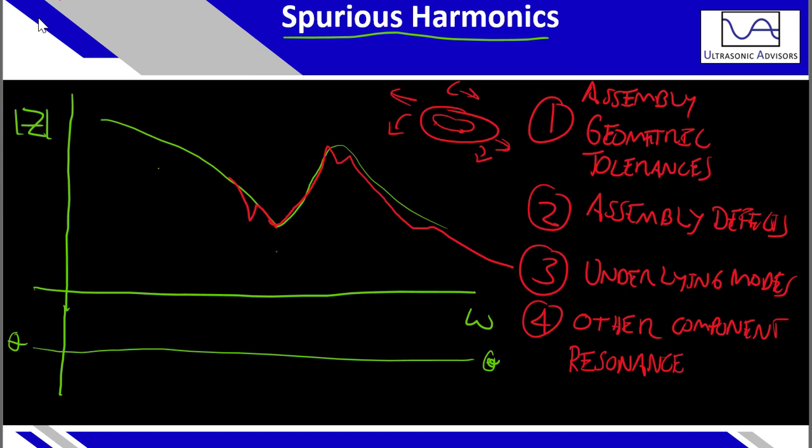But usually the ones that we really worry about in terms of the build quality, because these can be designed away in FEA, you can do a DOE with geometry. The assembly defects and geometrical tolerances are harder to capture and monitor. They may be more sensitive for a particular design of a device, and you don't know about these modes until you actually build your device. Hence, it's important not to stay in your finite element realm for too long.